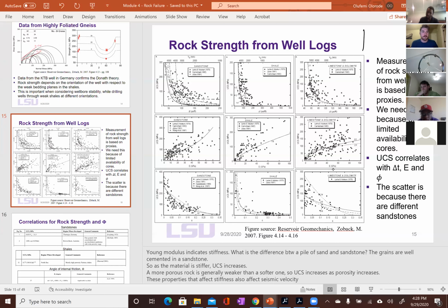So a material point in the domain will be some region in the material that you have marked as, say, this is region A, so that when the material deforms, you still have the general idea of that position of the material in the object. So region A is still this material. So you are following that material point as it deforms and all. That's the Lagrangian. And this whole thing can actually move, right? Maybe it was here before. Let's say air is moving, right? The air molecule was here before. That's a material point. But now it's here. You continue to do the calculation on that material. You follow it as it evolves through the domain.